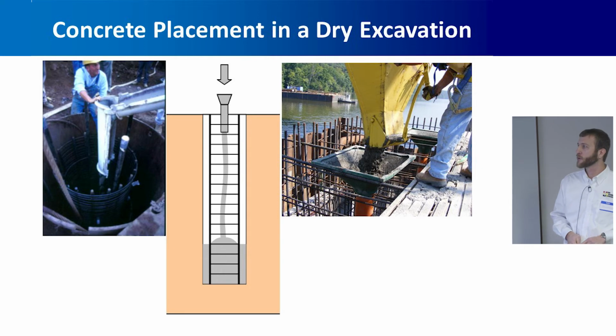Then it's time to place concrete. As I said, with a dry excavation, it is acceptable to free fall concrete. You just need to make sure that it's not hitting the cage on the way down, which can cause segregation and other problems.